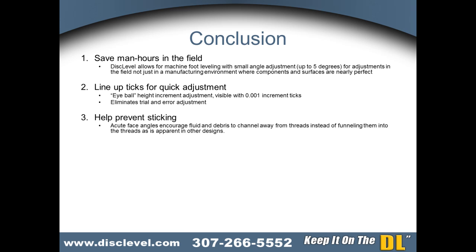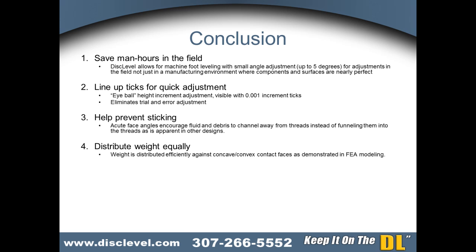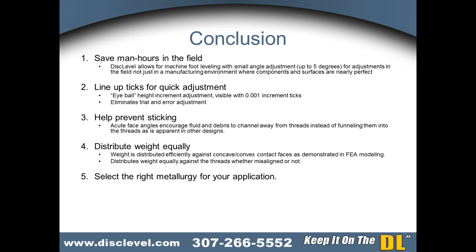Help prevent sticking. Acute face angles encourage fluid and debris to channel away from the threads instead of tunneling them into the threads, as is apparent in other designs. Distribute weight equally. Weight is distributed efficiently against concave-convex contact faces as demonstrated in FEA modeling, and distributes weight equally against the threads whether misaligned or not. Select the right metallurgy for your application, whether for marine applications, gas compressors, or other heavy equipment leveling.